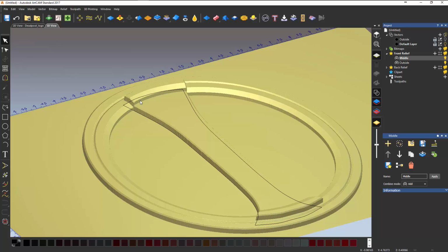Okay, so for this instance, as I mentioned before, if you've used combine modes like in the shape editor or two-rail sweep, you would know when putting two images together that should blend to one another, we could simply set that to merge high. And I'm going to do that in this case. Going to drop my combine mode, set to merge high, and we can see that's blended in nicely as we would expect it to.